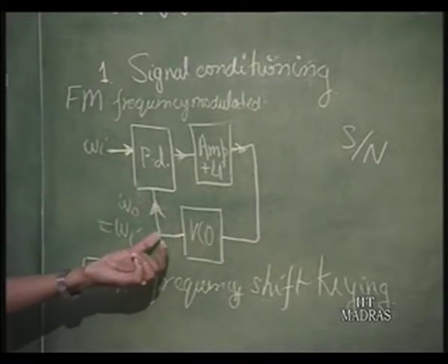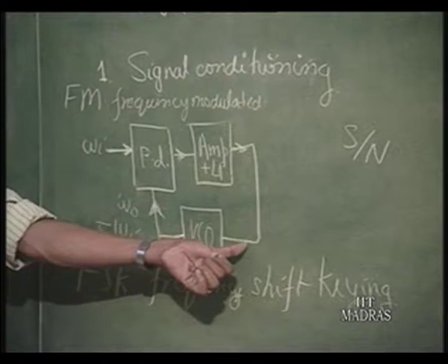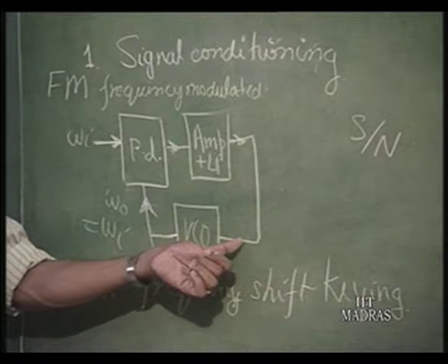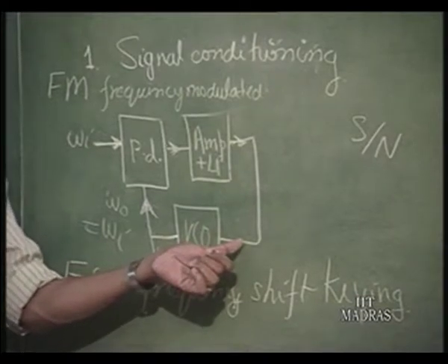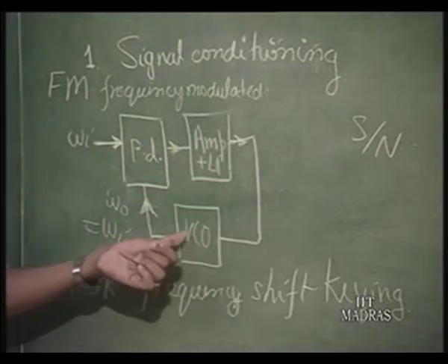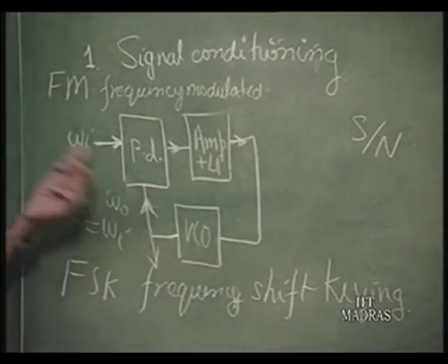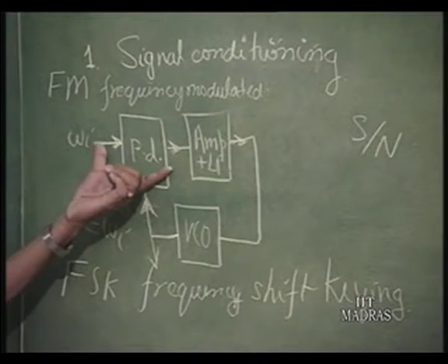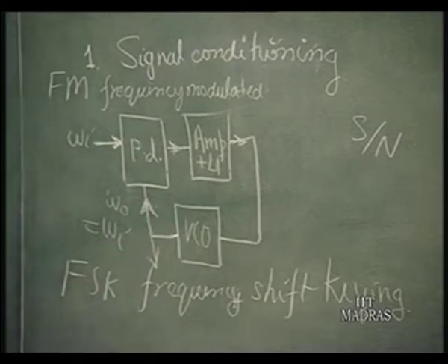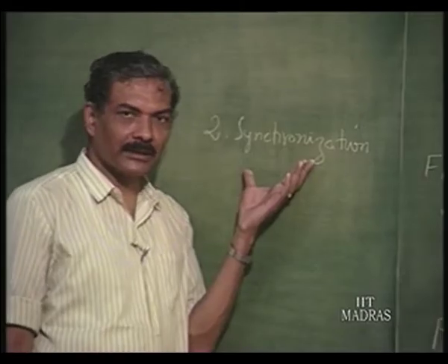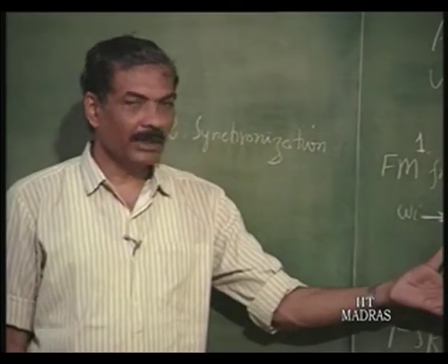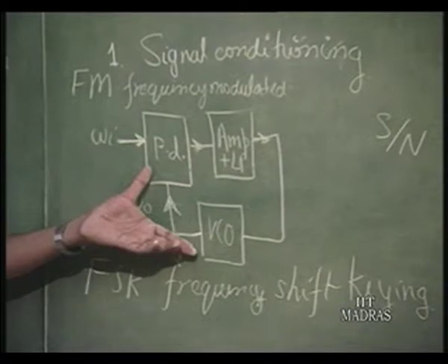So, this will learn about what kind of DC voltage it has to maintain. Okay. During other times, this gets disconnected, or it will slowly discharge, but because there is a large capacitor here, it will not deviate from that value, okay, until the next set of pulses come into picture, and again it is restored. Okay. So, extracting the horizontal or the vertical synchronization pulse from the composite video signal can also be done by using a phase lock loop.